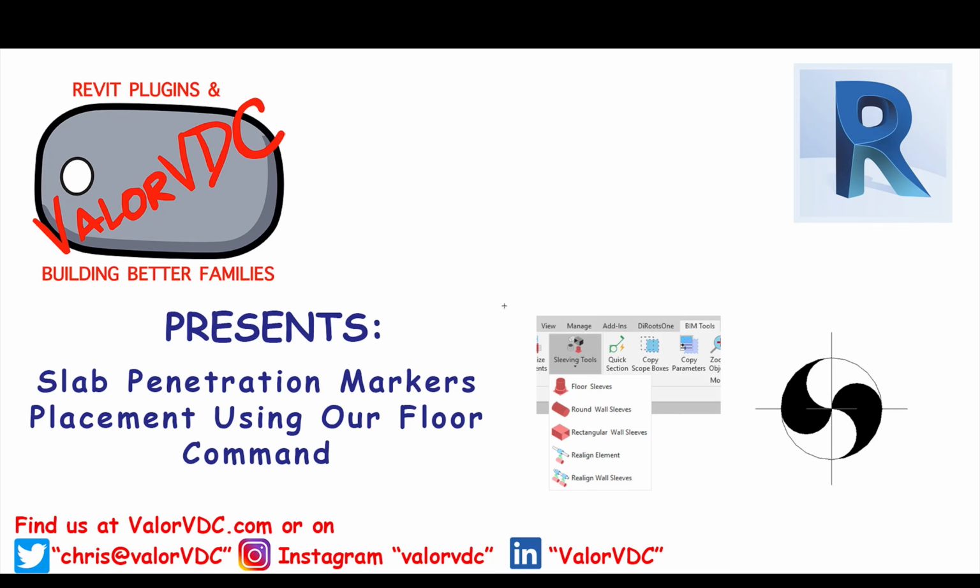Today I'd like to talk about slab penetration drawings. Not sleeve drawings. These are the drawings that show where all your pipes penetrate the slab so the GC can verify that you have all your turnups accounted for and they don't have to cut their nice, new, pretty poured slab.